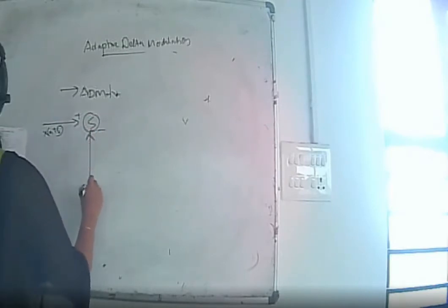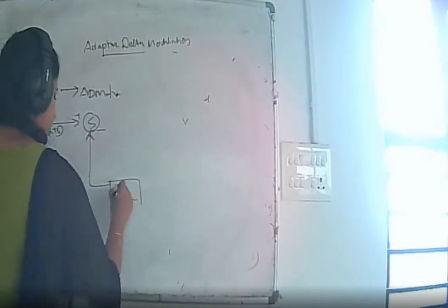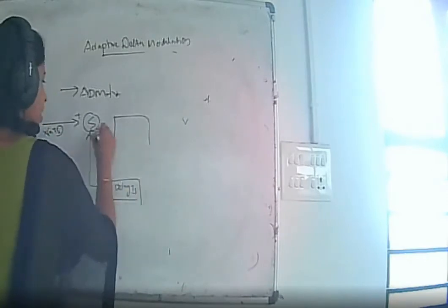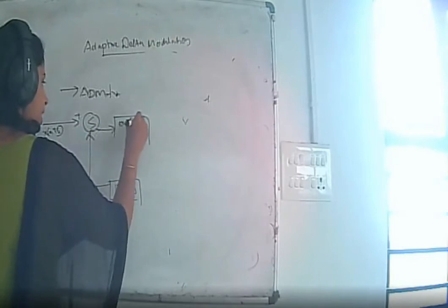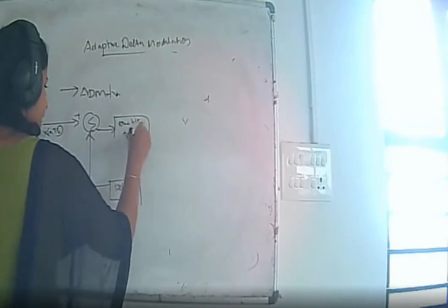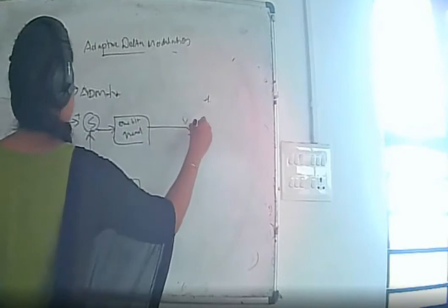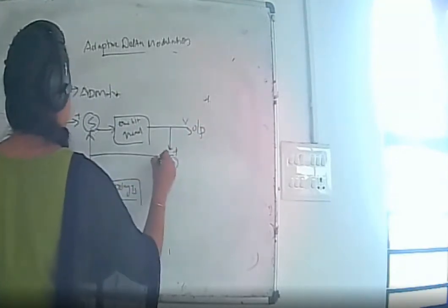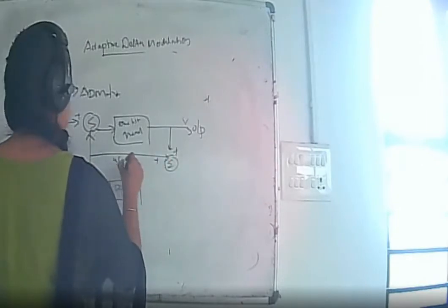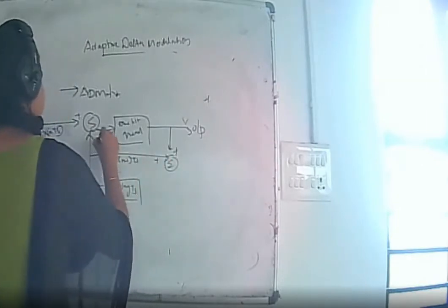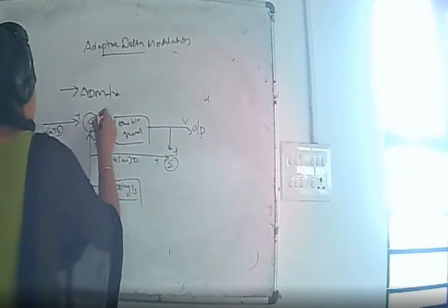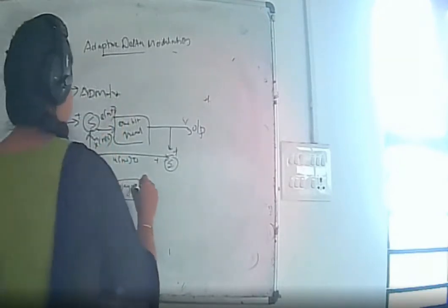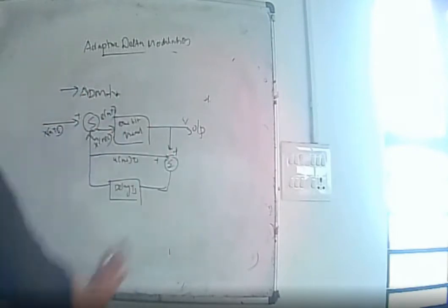Here, we have a delay circuit of time period Ts, and it is given to a 1-bit quantizer, as in case of delta modulator. And the output B of nTs is given to a summer, and this is our delayed version, and this is our X cap of nTs, and this is our E of nTs, which is the error signal, and this is our delta modulator transmitter.